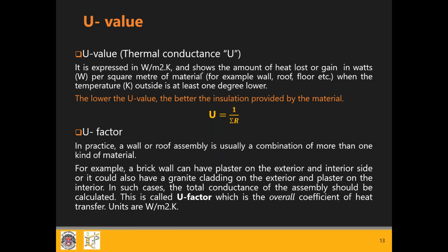So that means over 1 square meter of wall area, how many watts are transferred through if my delta T, that means the temperature outside, changes by 1 degree or say 1 Kelvin, right? So that is what U value is.